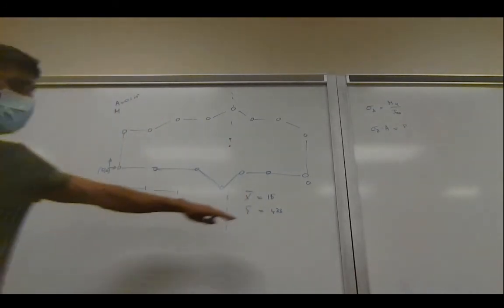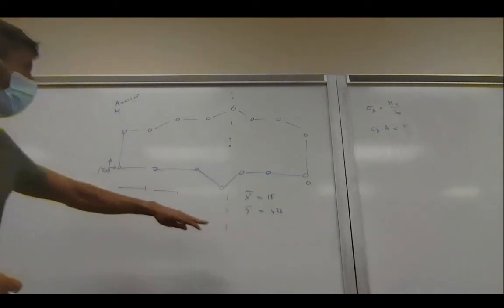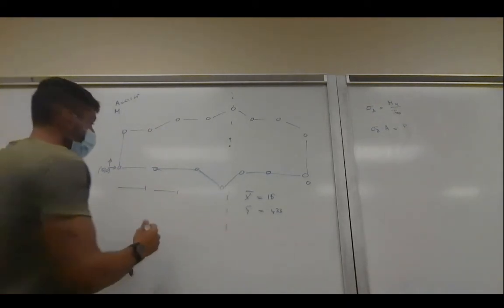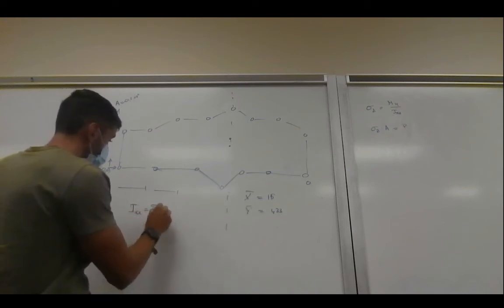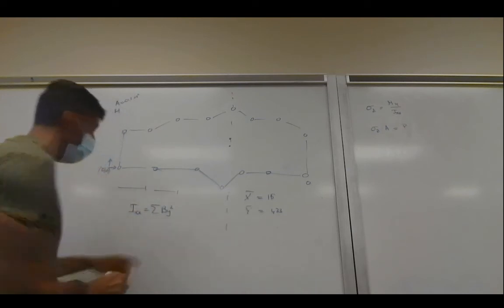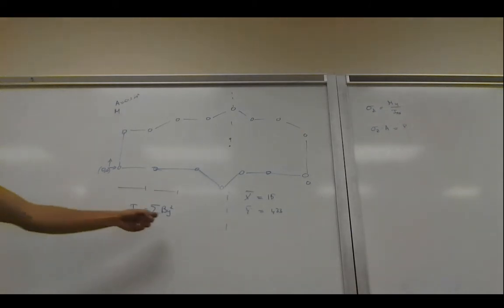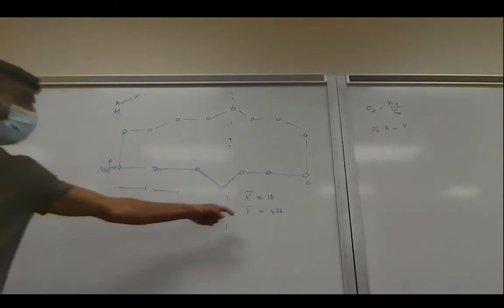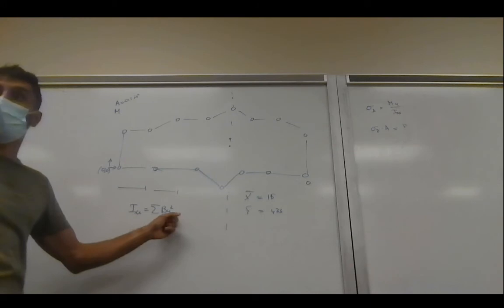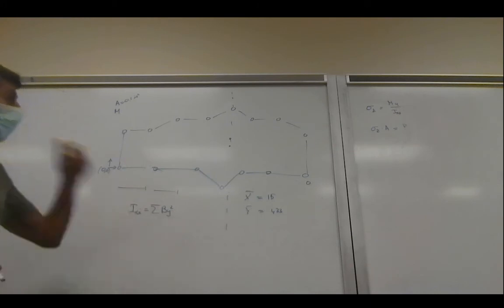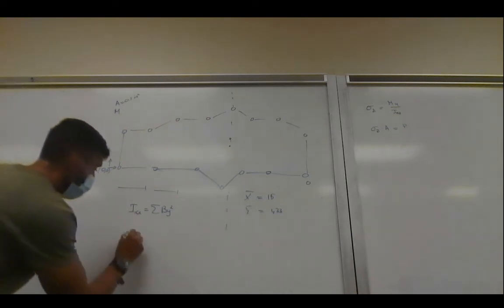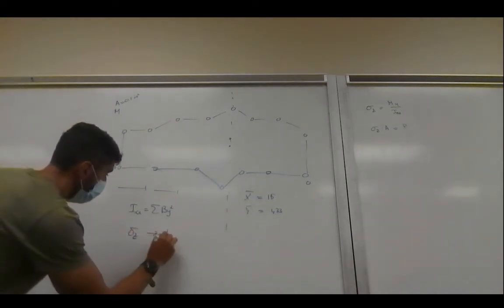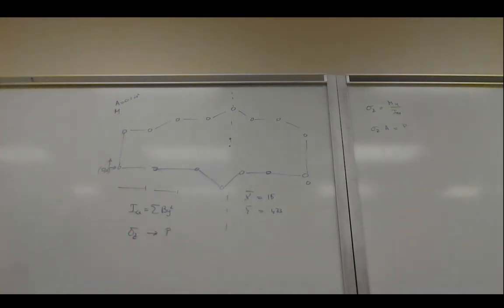So you have to calculate the centroid first. Using the centroid, you could calculate the moment of inertia, which was just simple. You could just do Ay squared, right? And this y squared, you have to fill in the right y distance. And then you could plug in to get the stresses, and from stresses you could multiply with area to get loads.